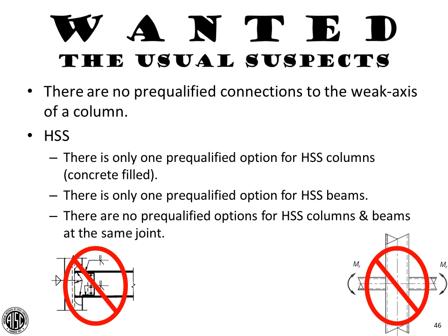If you have orthogonal framing at a common column with moment frames, you can sort of get around that problem because AISC 358 has some built-up sections that can be used to essentially provide 4 flanges around the column. So they have cruciform sections, box sections, and plated wide flange sections, and so that's an option. But simply framing to the web of the column is not an option.